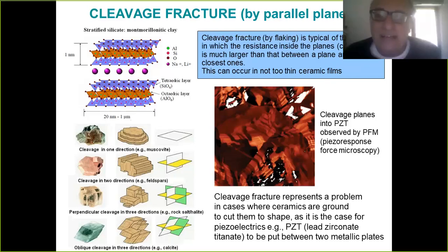The problem is that you have a case, of course, which includes the piezoelectric. The case is not a problem itself. I can make a steel case. But inside I have a ceramic, which is the real PZT, the real piezoelectric. And I have to cut the ceramic to shape in order to allow it to work and to fix the case, which in some cases is not obvious. Remember that ceramics and steel in most cases are produced by cutting them to shape.